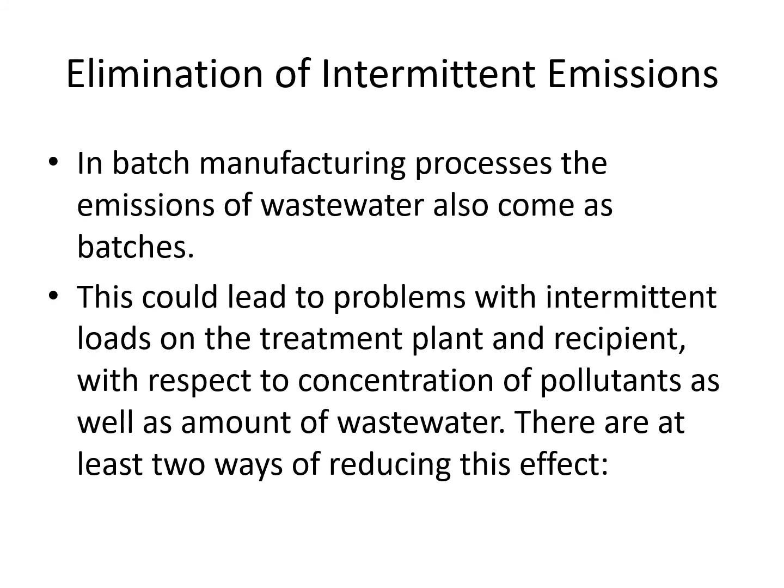now please go through the cooling water, sanitary water. It is on the same pattern, storm water, and elimination of intermittent emissions in batch manufacturing process. The emission of wastewater also comes as batches. This could lead to problems with intermittent loads on the treatment plant and the recipient with respect to concentration of pollutants as well as amount of wastewater. Therefore, so there are at least two ways of reducing this effect.